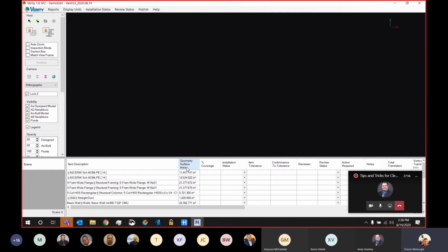And then that would be, for example, I keep coming back to it, like the bolts. If those are modeled, especially for a very high level of detail model, I'll clean those out because that's just extra elements that'll slow down our analysis, especially if we're interested in the major steel structural sections.